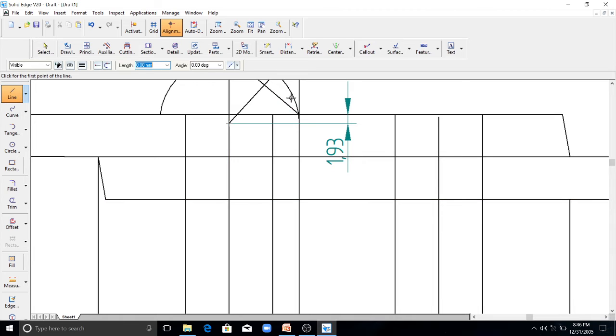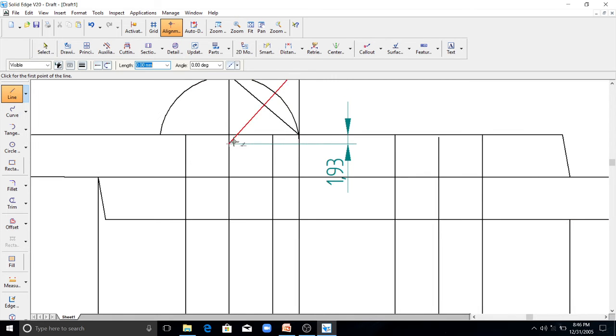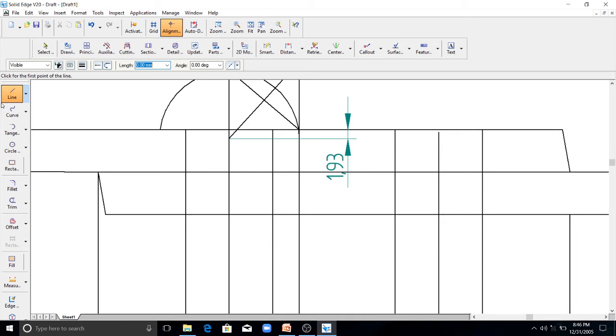So instead of drawing these things, I am telling you the simple technique. Just copy this distance here and leave that distance here, so you'll get the new center for drawing the bottom portion of the snap head. The radius remains the same, that is 0.8d. So 1.93 from this line inside.